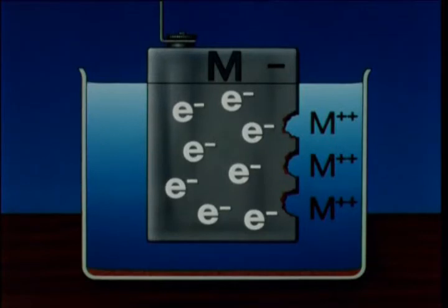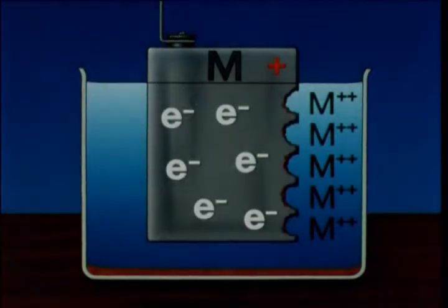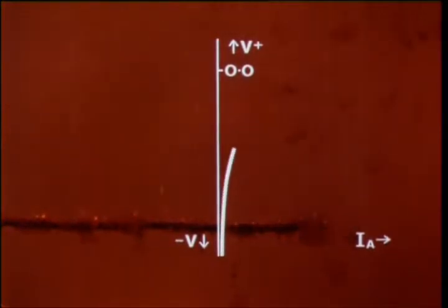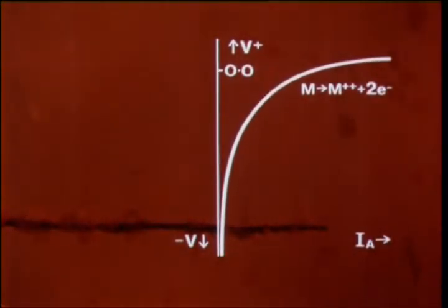As we have seen, by extracting electrons from the metal, the potential becomes more positive, and the rate of corrosion and the rate of producing electrons, that is the current, increases. When the corrosion product is visible, as the potential becomes more positive, the corrosion rate and the current increase visibly. This measures the anodic reaction rate.